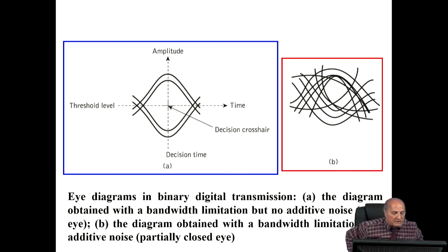Look at this figure, what is called the eye diagram. The eye diagram is simply a geometric locus of the various patterns in this case. I mean, there is a sample under decision, maybe, for example, state 1, but the one before is logic 1 and after it logic 0, or in other cases 0, 0, 1, 0, 0, 1, and the sample under investigation is subject to various variations.